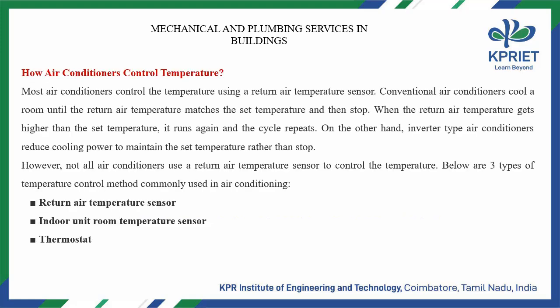How air conditioners control temperature. Most air conditioners control the temperature using a return air temperature sensor. Conventional air conditioners cool a room until the return air temperature matches the set temperature and then stop. When the return air temperature gets higher than the set temperature, it runs again and the cycle repeats. On the other hand, inverter-type air conditioners reduce cooling power to maintain the set temperature rather than stop.